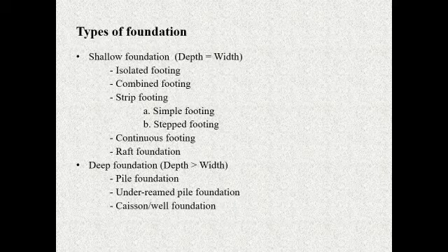And there are two major classifications of foundation. First one is the shallow foundation and second is the deep foundation. When the depth is equal to the width, then it comes under the shallow foundation. There are isolated footing, combined footing, strip footing, continuous footing and raft foundation. These are all the footings which come under the shallow foundation.